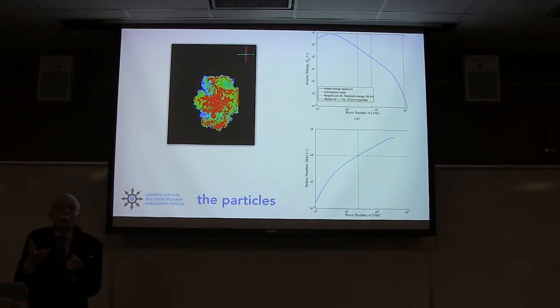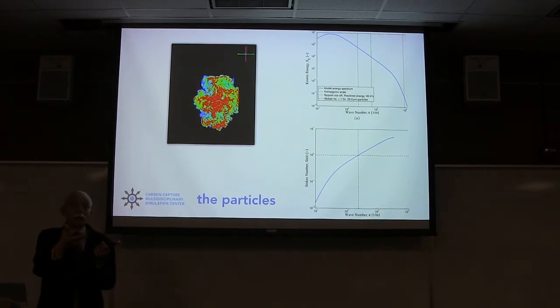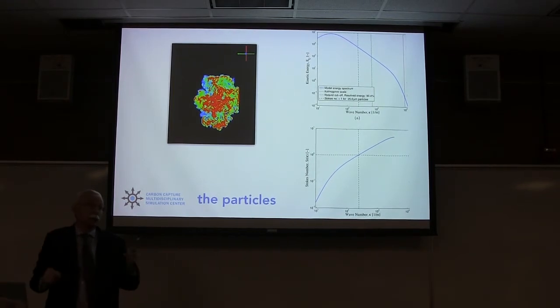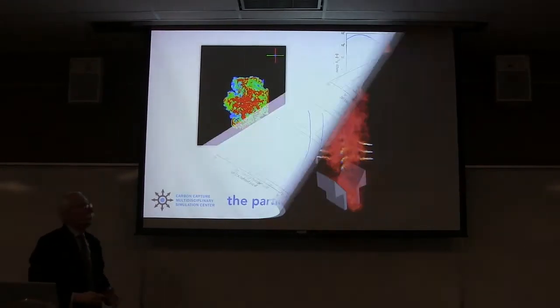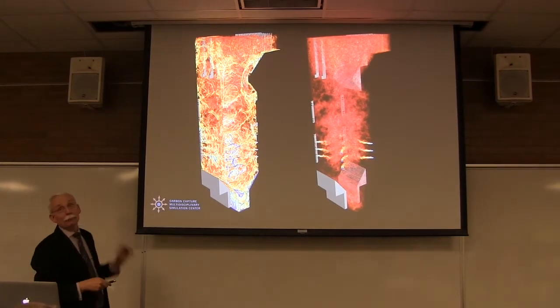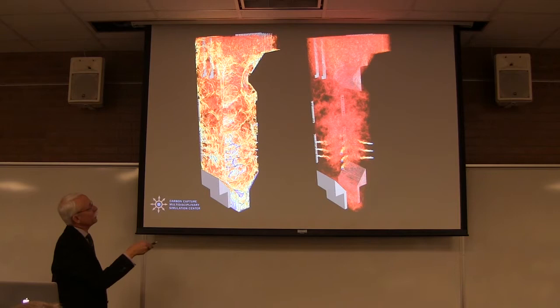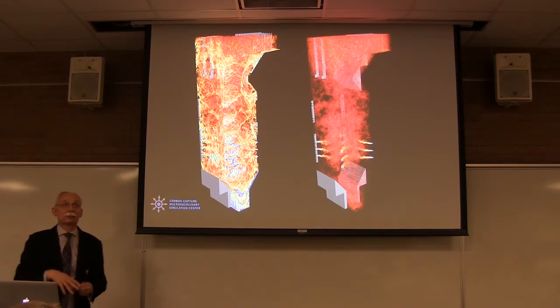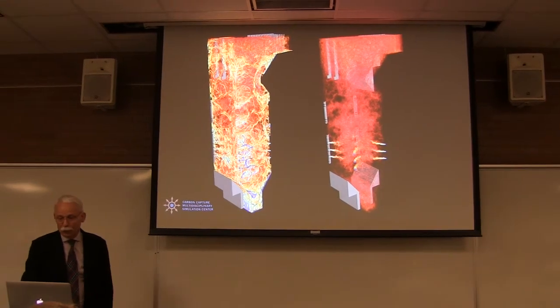The little ones are the ones that end up creating the ignition processes that are occurring in the system. The big ones go on for longer and are radiating to different locations. Where these particles are is a big deal. So in that computation, here's where the 70 micron particles are in the entire boiler through a volume rendered image at one point, and there are the small particles in those systems. There's the information we're resolving.